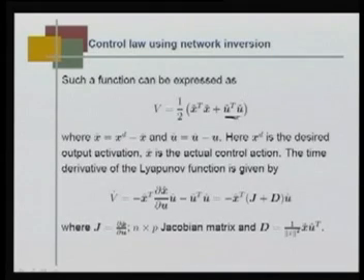So, with the introduction of this new term, we take the time derivative of the Lyapunov function, and you will see that if I differentiate this term, x tilde transpose x tilde dot, x tilde dot can be written as minus dou x upon dou u, so that is why the minus sign comes into dou u by dt. So that is how the first term comes. The second term is u tilde transpose into u dot, where we can write this term as minus x tilde transpose (J plus D) u dot, where J is dou x upon dou u and D is 1 upon x tilde norm square, x tilde u tilde transpose.